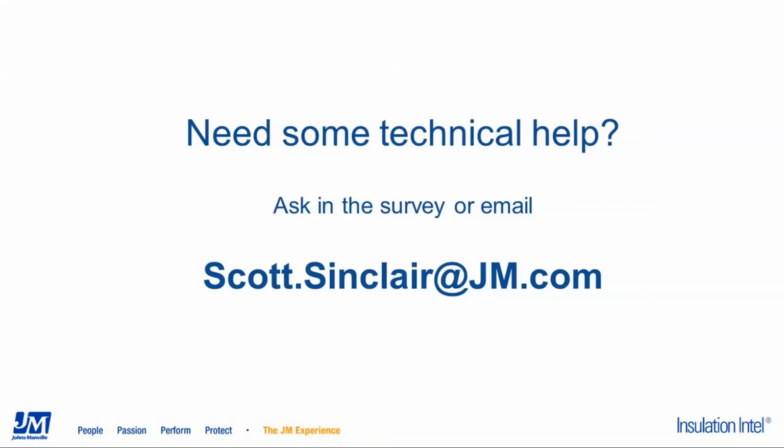Understood. And then Scott, this is a question I know you addressed, but just to clarify this for the group, can the corrosion inhibitor be applied to existing in-service piping being re-insulated to inhibit further corrosion? I know you talked about this, but if you just want to reiterate that for the group. No, absolutely. The key is the corrosion inhibitor is not a standalone material. It is integral to the chemistry of the insulation. So to answer the question specifically, it can be applied, but it's applied by installing the insulation on that existing in-service piping with the insulation having the XOX package in it. So it's not a separate compound or material that you can apply to the piping.